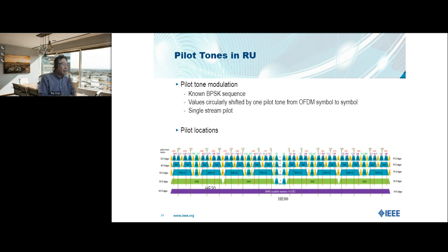The purpose of that precoding matrix is to split the data across different spatial streams, so that the different streams have different data and we can achieve MIMO, multi-input, multi-output. You can transmit more spatial streams, which means more data in the same frequency and time. But for the pilots, single stream pilots, when you transmit them you don't need to split them because tracking uses a single stream pilot.